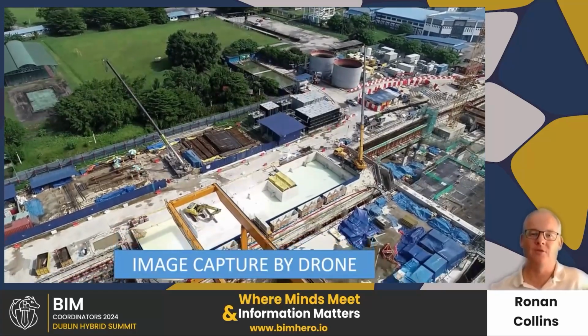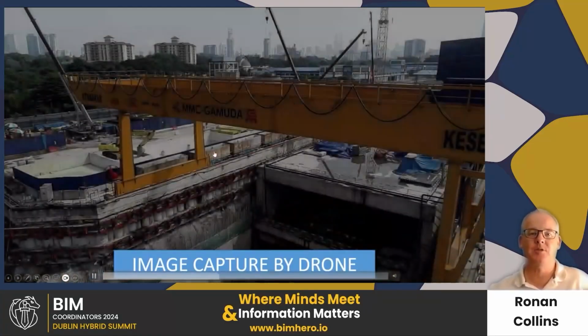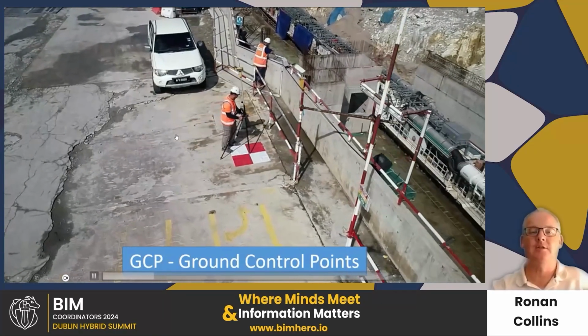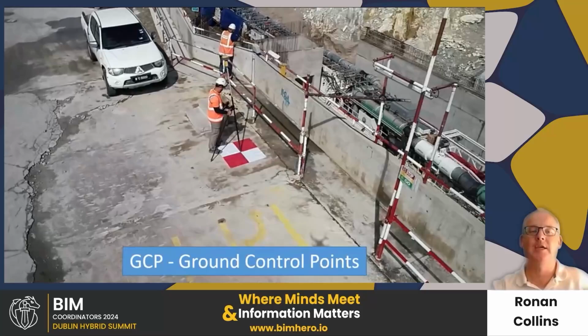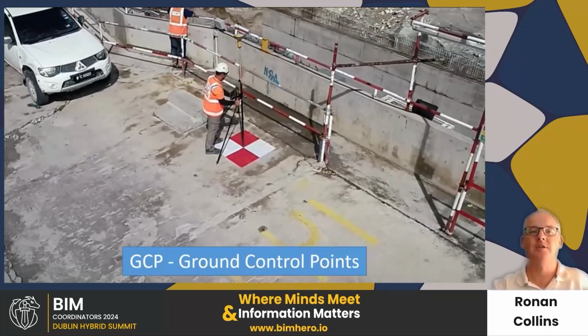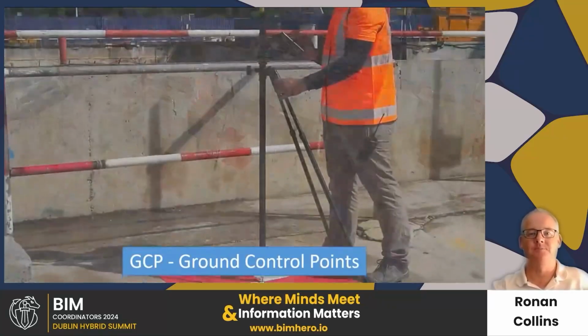So the drone flies over the site. It captures images which overlap by about 70%. And then from that, they can generate the data that we need to bring it into the BIM environment. One key part of this is to have ground control points, and that's why the surveyors are the ones that do the drones. So they know where they are, they know what's going on.